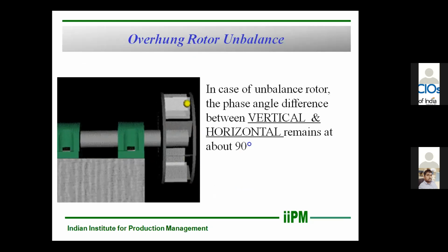And now you are covering how we acquire data, and once we have acquired data, how we interpret that data to arrive at the precise reason for this high vibration. It could be a frequency parameter, the amplitude parameter, or the acceleration or velocity parameter. Based on that, we make an interpretation to narrow down the precise reason, so that we can act on it and rectify the reason at the next available opportunity.